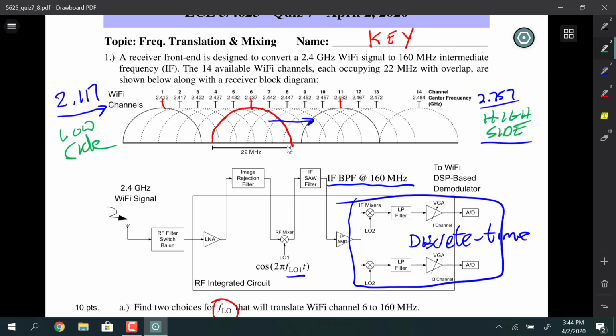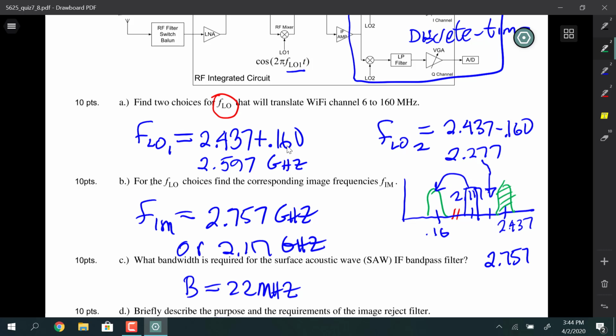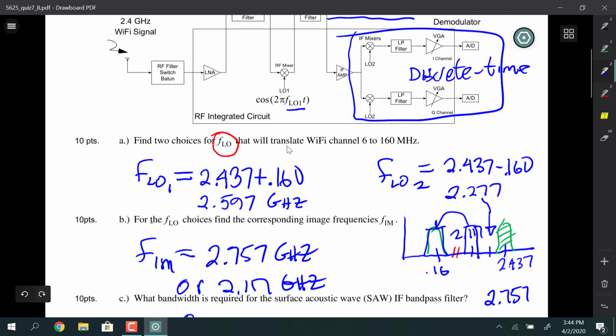We're not emitting frequencies intentionally. These are frequencies that our receiver could receive and would land on top of. Like in this picture over here, I was trying to say if we're in the low side tuning, that signal will land right on top of the green signal that we want to get. The image will, unfortunately, going to have that happen.